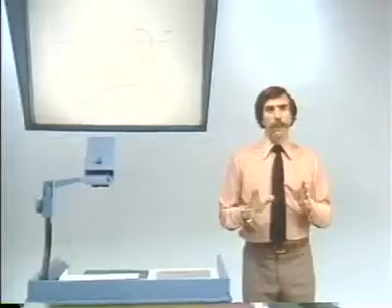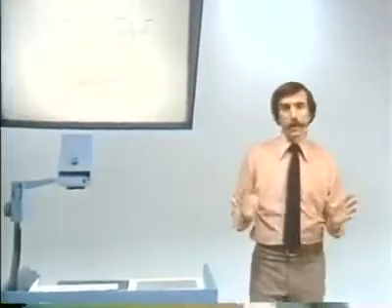Now, notice in this that there's no issue of aliasing. What's happened is that we've replaced S by a function of Z, and it corresponds to mapping the S-plane to the Z-plane. In fact, the whole j omega axis has mapped to once around the unit circle, which obviously requires some type of nonlinear mapping because, look, the j omega axis is infinitely long. The unit circle has a finite radius.